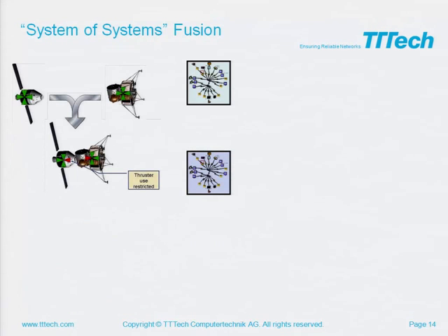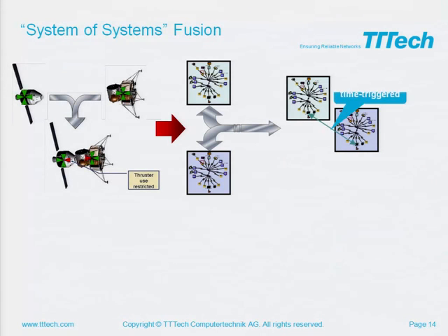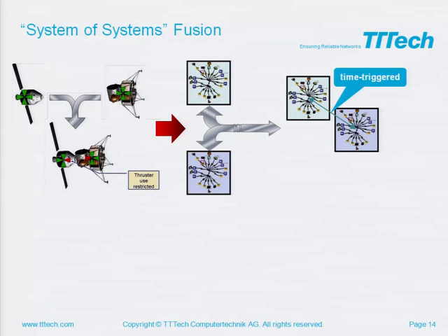I want to show you a slide, for example, from the NASA Orion context. It's a slide from NASA or from Honeywell. Here there are different mission scenarios where this synchronization would really make a lot of sense for control. For example, we have this Orion vehicle that's docking to a lander, and we have two networks which are integrated during the docking maneuver. We want to have time-triggered traffic here, because the capsule wants to control the lander vehicle. This means we have control loops during the landing, and therefore